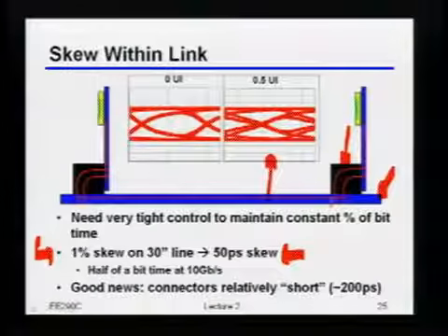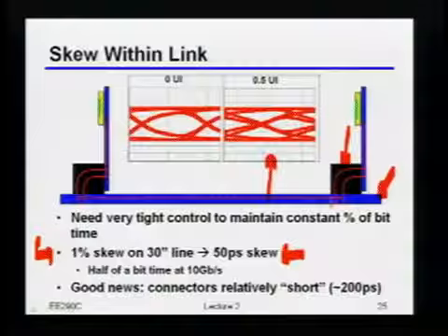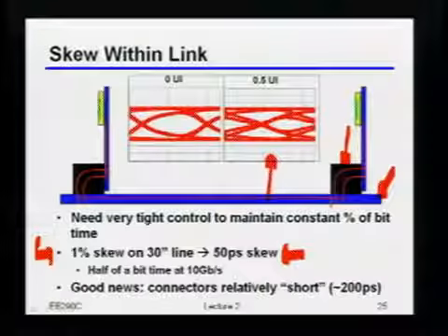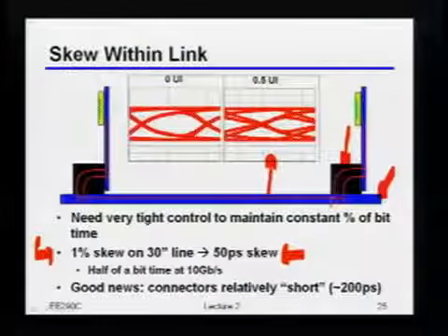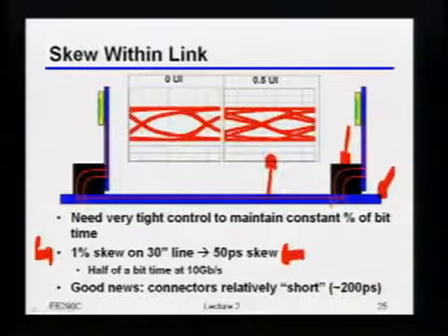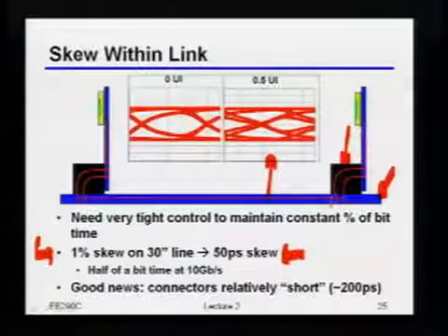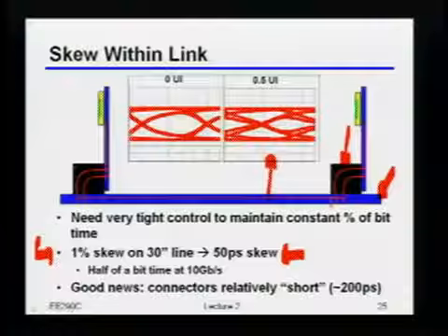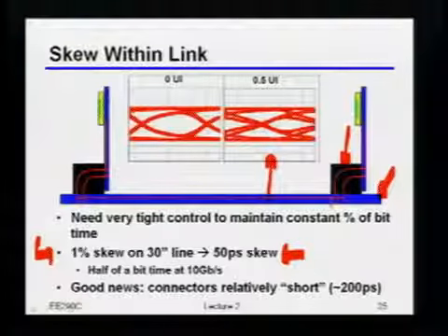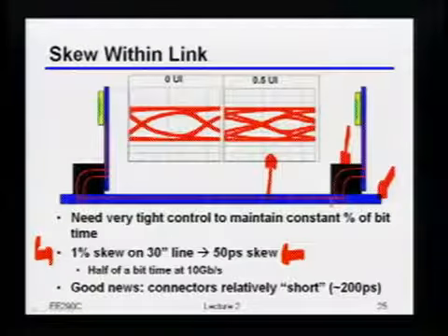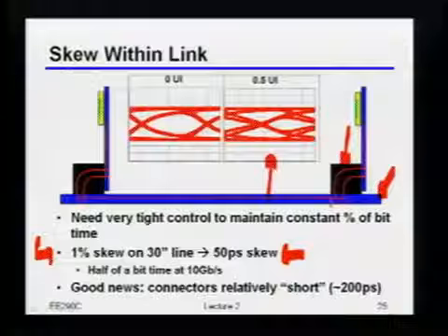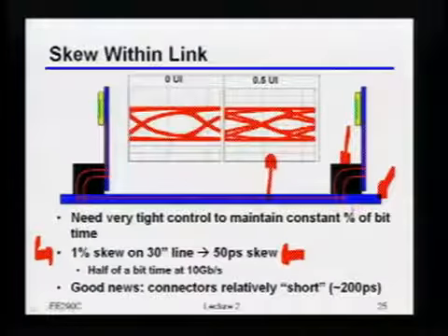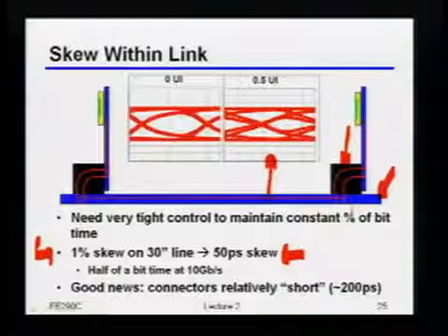Yeah, Shiva, question? Yeah, so how do you compensate for it with all these process variations? Okay, so the good and the bad news is there's a little bit less that can vary in PCBs than, for example, in a transistor, right? Because there's just not that many different things going on in the PCB. Okay, so it turns out kind of the biggest sources of variations on the PCB are just things like temperature, humidity, things like that.